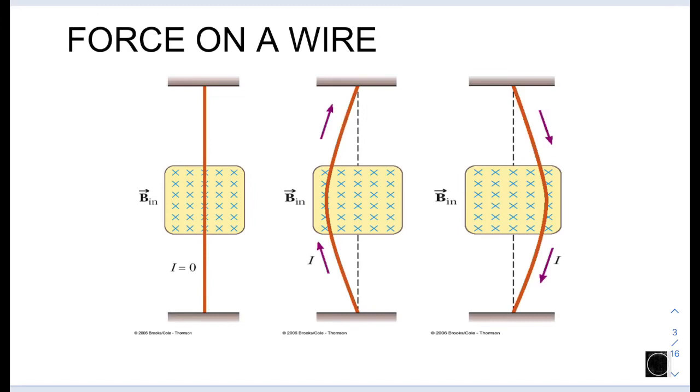By using the right hand rule, everyone, you have to follow me, you have to try together with me. Now touch the screen. Your B is into the page. Your velocity direction now is the same as the current direction. Instead of V, your index finger is now the direction of your current. Your current is upward, so the index finger is upward. If you see here, your thumb is pointing to the left, meaning that the force experienced by the straight conductor having current flowing upward will be to the left. That is why the middle section here is skewed or pushed to the left.